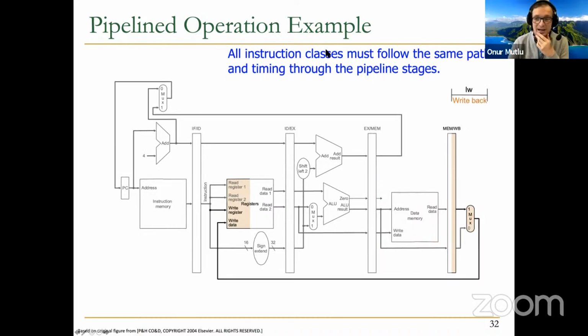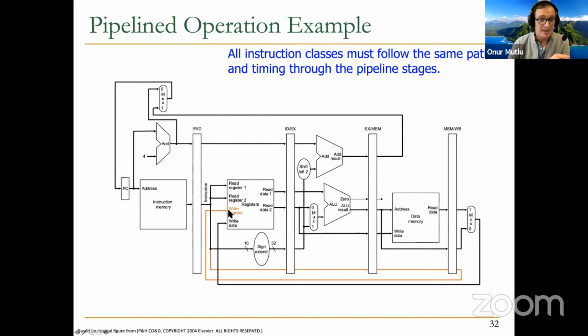So I think you need to be careful with this write data that's coming from load word. You need to write the correct data coming from memory, and you need to write it to the correct register. So when load word is being executed, you need to propagate the right write register ID so that you use the correct write register ID that belongs to the load word.